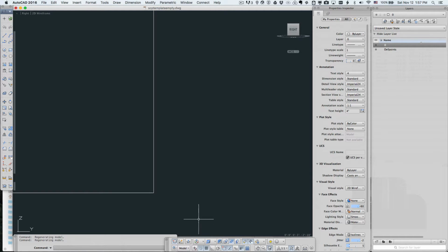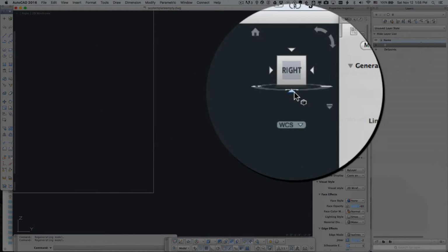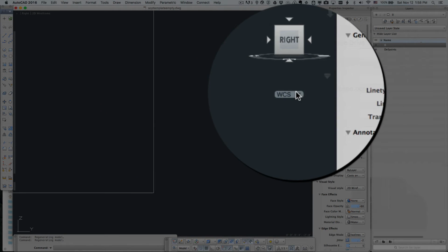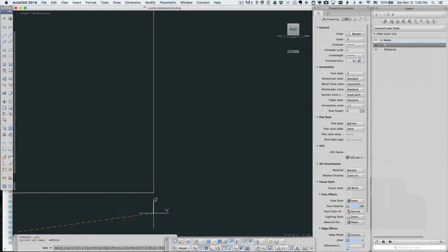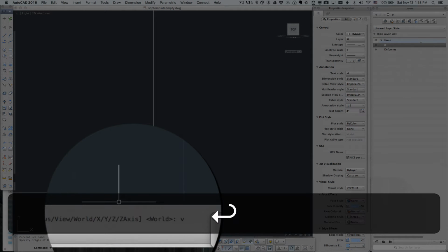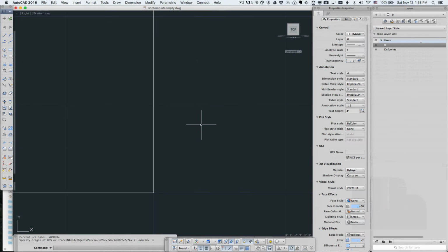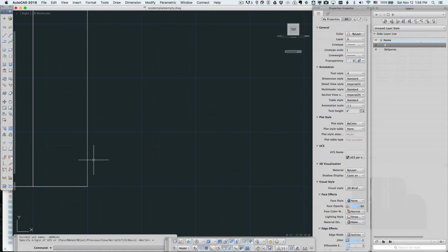So we're going to need to draw a flange shape, and we're going to use the sweep tool for that. But to draw the flange shape, I need to use the polyline tool, and to use that I need to be in top view instead of right view. So we need a new UCS. So the UCS tool I'm going to use here, so we want this view right here because we're at the side, is just V for view.